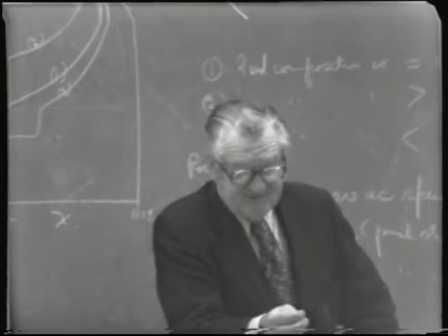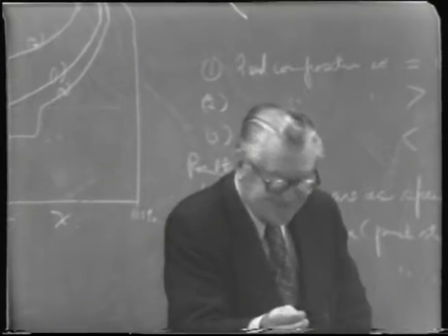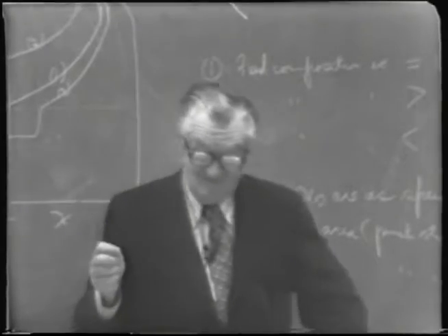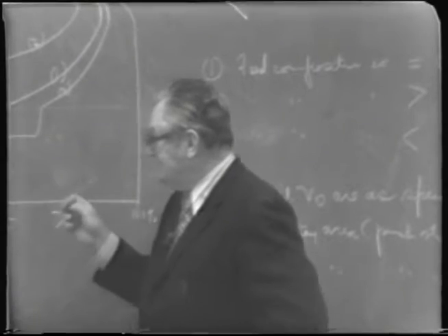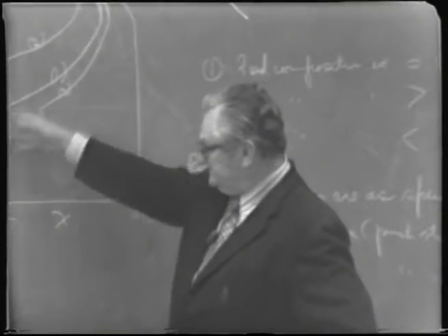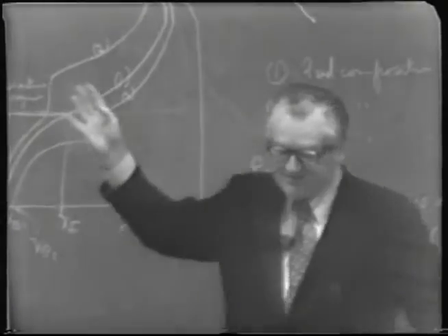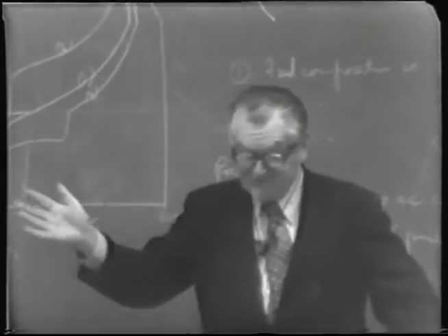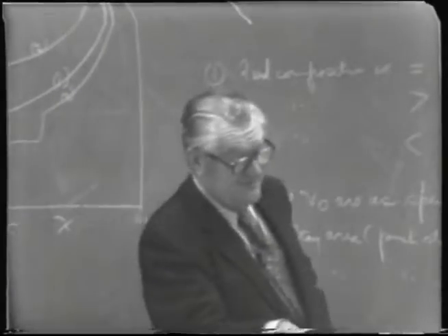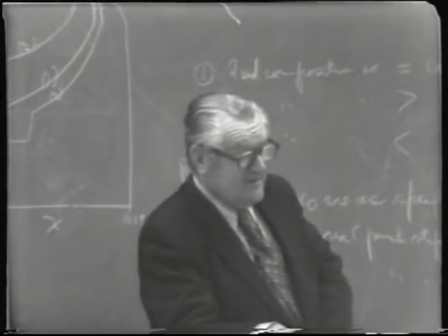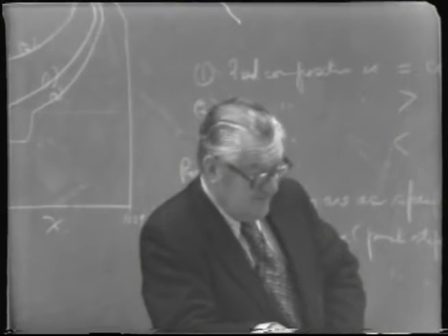So the operators have found in practice that by operating the rectifying section in such a way as I've indicated here, so that you have some inactive trays above the feed, they're able to get the stripping down to the desired value by operating it in this fashion.